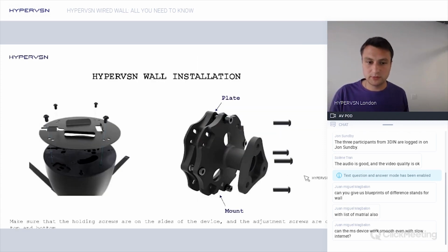Let me open the picture of the mount so you understand better. Left and right bolts are used to fix the device on the mount. So these bolts are holding the device. The device won't fall down if 2 bolts are fixed. Then when the device is fixed, pay attention to the bottom screw on the mount. The bottom screw is used for the mechanical calibration of the device. With the help of this bottom screw, you change the positioning of the device. You change its angle.